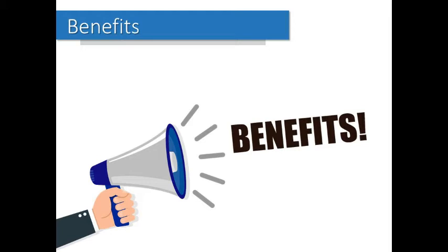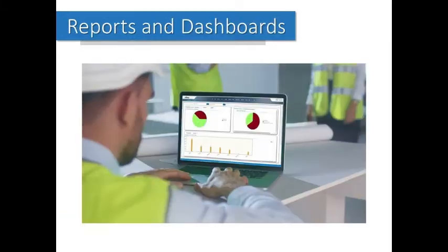But in this particular case, they had no system in place. So the next technician went in and replaced the thermostat. Then they got another hot-cold call and they replaced the thermostat again. This happened five times in the same room at $75 a thermostat, and it wasn't even the thermostat at all. KPIs give you an overall insight that could not only save you money, but also increase production or, in some facilities, productivity.